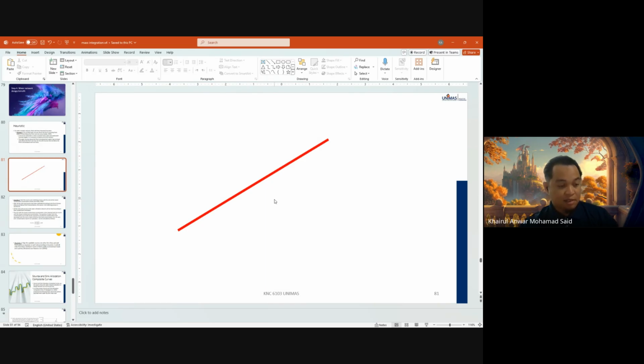Next, the second golden heuristic is prioritize low concentration sink. So reserve your highest quality water or fresh water for the sink that has the strictest purity constraint. Next, the third one is match high with high. So match source with high contaminant level to sink that can tolerate high contaminant level to maximize the driving force.